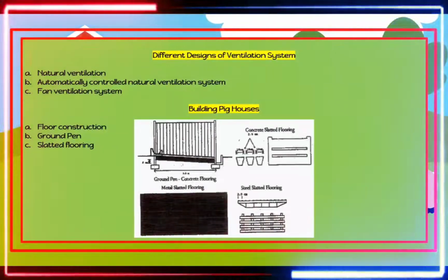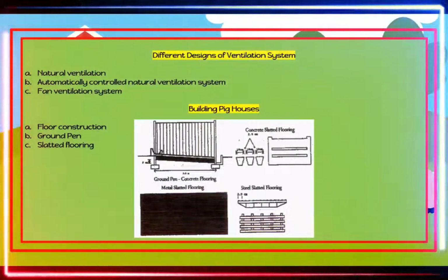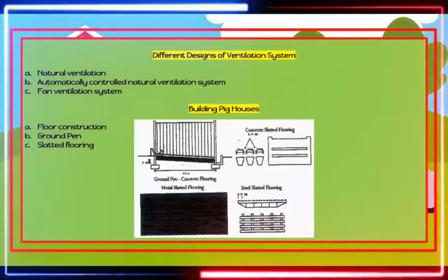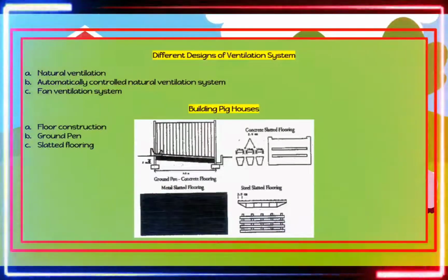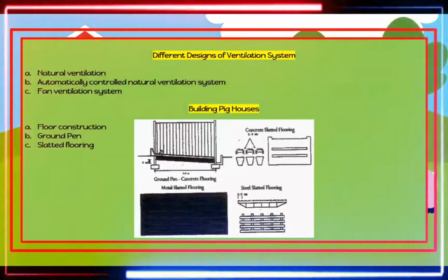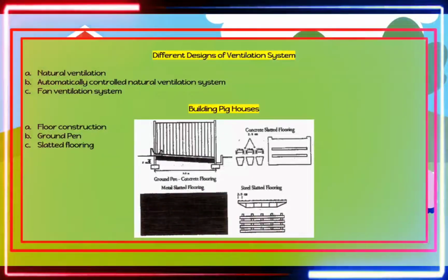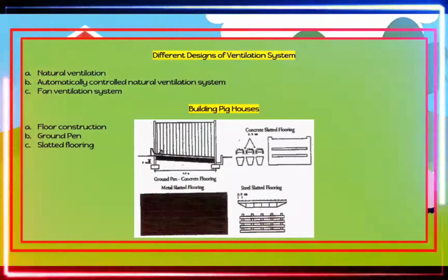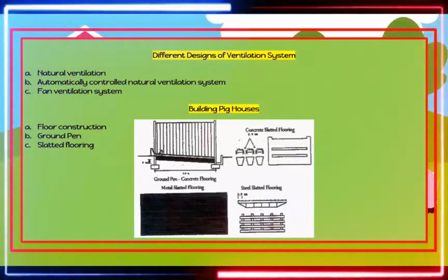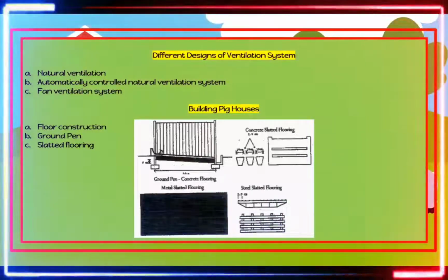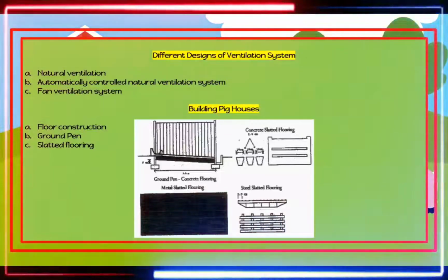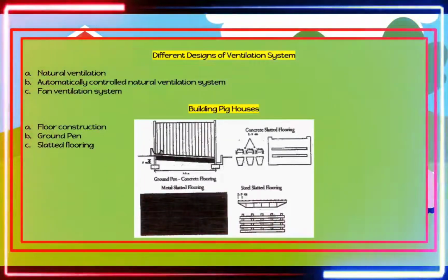As much as possible, the walls should have holes or GI pipes or steel bars or railings to ensure airflow. Although high perimeter walls are needed for security reasons, it is wiser to use barbed wire or posts with barbed wire. Construction of very wide houses does not prevent ventilation problems. On the other hand, wide houses are not very efficient in heat exchange, since accumulation of body heat by the pigs increases the temperature inside the house. To be efficient, the width of the house should not be more than 10 meters.